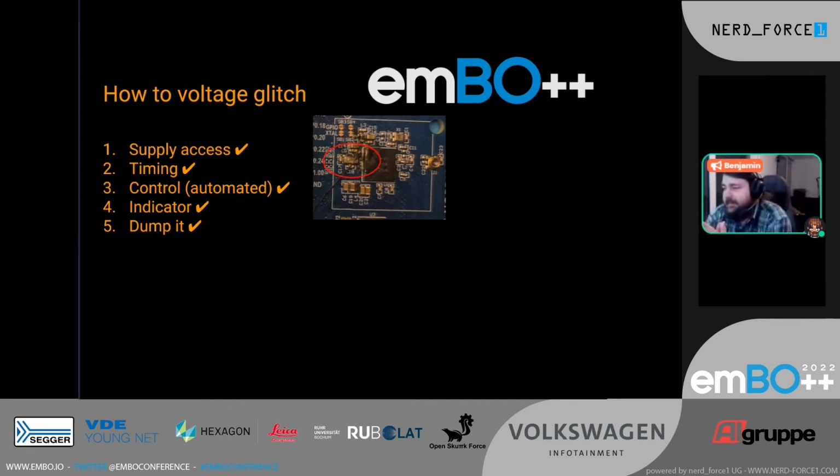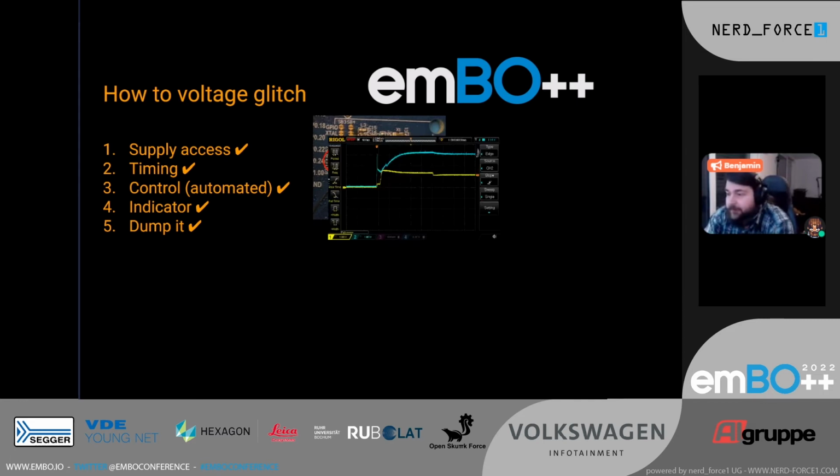it has been a process. So just to give you a rough idea what we just went through: we figured out where we connect our wire to both send the voltage and glitch the voltage. We figured out what the timing should be using our oscilloscope to locate the point in time where we should start our glitch.